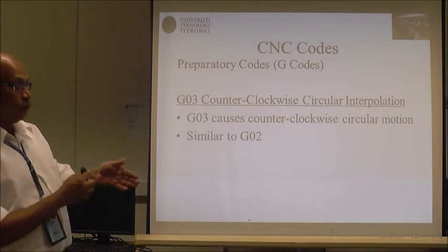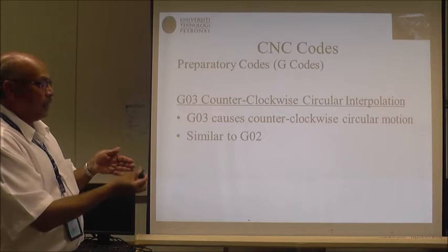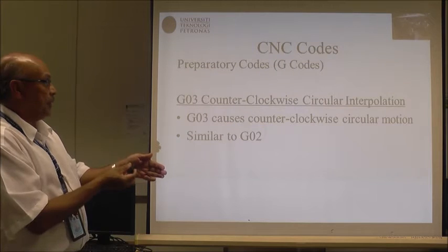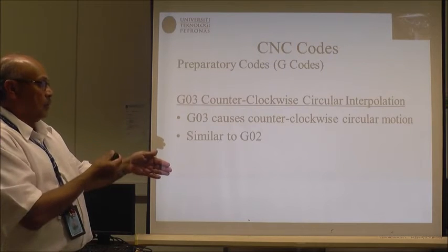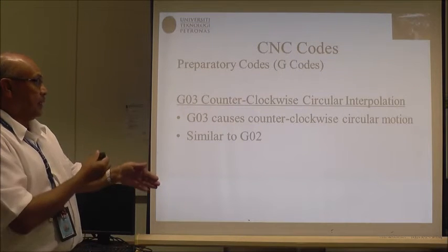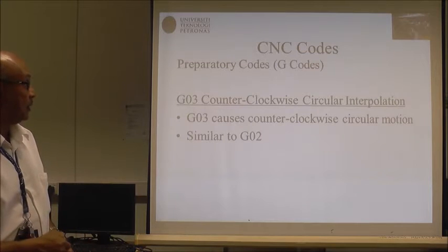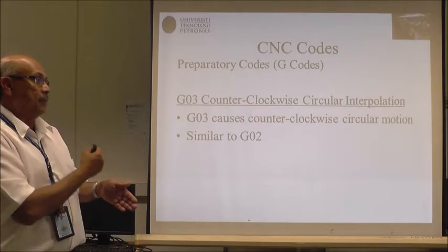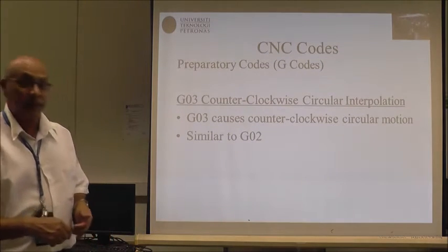And just now G02 moves clockwise, G03 moves counterclockwise. So if we are at the same position here, it will move counterclockwise, reverse from the clockwise direction, and you need to give the X, Y and the feed rate, it will move to that point. Alright, next slide.